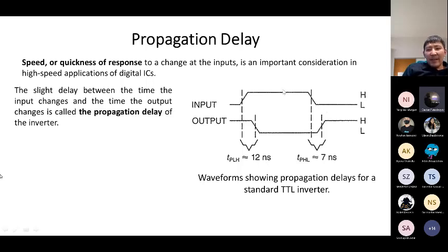But what's interesting here, look, for example, here you can see that when the input is high, the output of the inverter will be low. From this time you begin to decrease the input, and the input will go low, but you see that the output has some delay to respond, and this delay is about 7 nanoseconds. Can you see the difference? They're not the same, right?